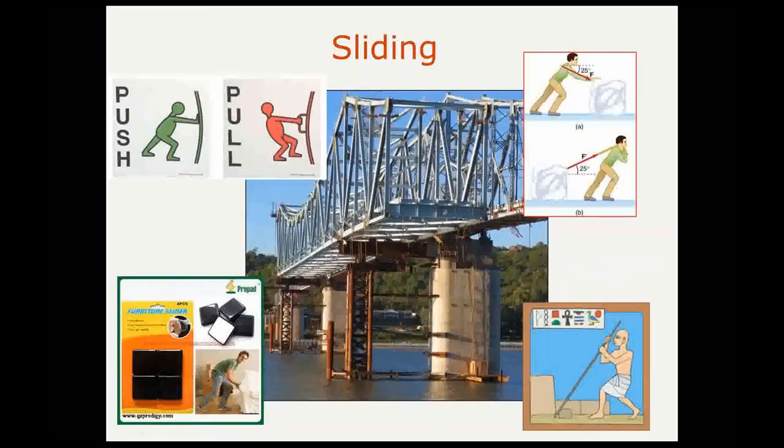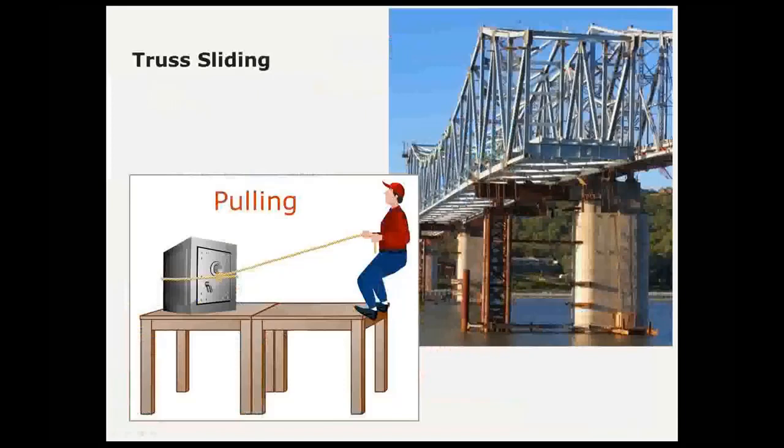And we were going to use PTFE sliding bearings to slide the bridge on a smooth steel surface from one pier to the other, and that's analogous to a furniture slider used to shove heavy furniture around on a smooth floor. So this is an analogy I think helps you understand the forces that are involved.